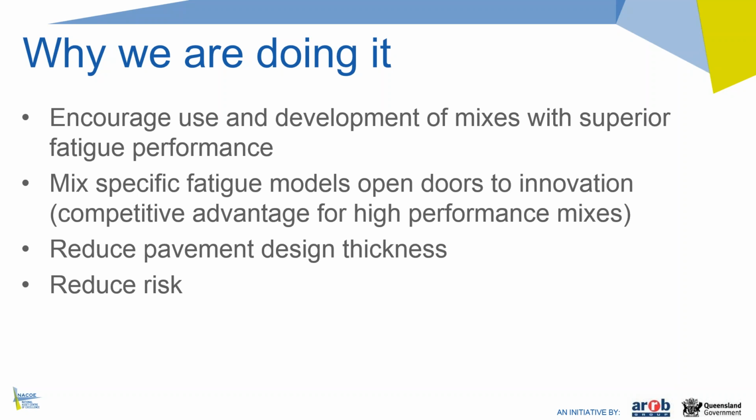And using those mix-specific fatigue models at the same time will open the doors to innovation, because when you're using mix-specific fatigue models in combination with mix-specific modulus functions or master curves, you can really get a competitive advantage if you're able to develop high-performance mixes, which is what we want to encourage. Because that will lead to reduced pavement thicknesses and will lead to more cost-effective pavements for the public.